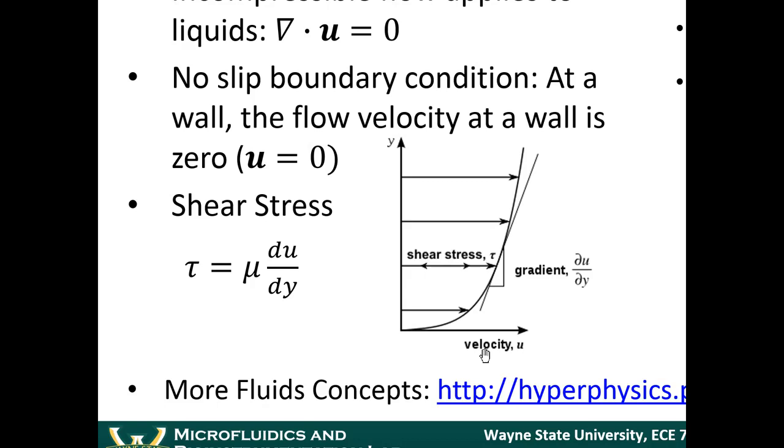This is a situation where we have fluid flowing through a channel, and this represents the bottom of the channel. And this side could be free, let's say. This is called Couette flow, by the way, C-O-U-E-T-T-E. This is where you have one wall and the other side is free.